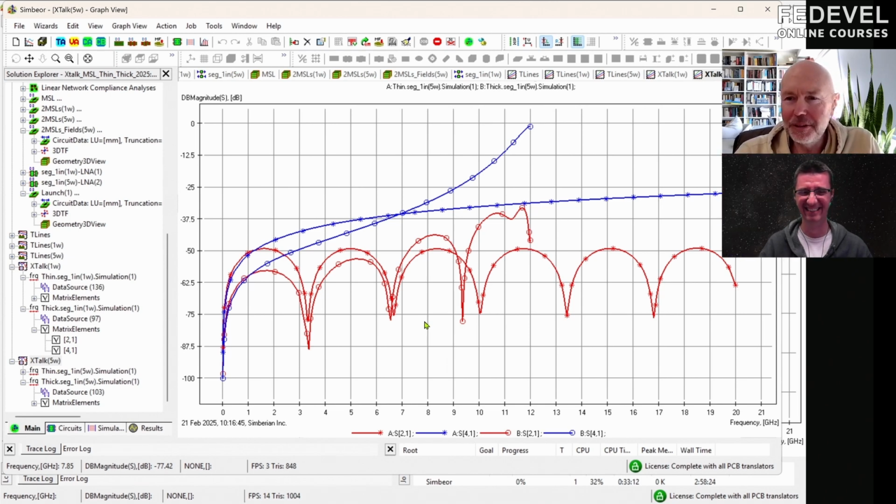But it depends on the context of where you do the evaluation of crosstalk, and that was my part on quantification in the crosstalk tutorial. The quantification part essentially explains different ways to look at the crosstalk. It starts with simple S parameters, or then power sum crosstalk. It's essentially the sum of all crosstalk, the sum of squares of all S parameters relevant to crosstalk.